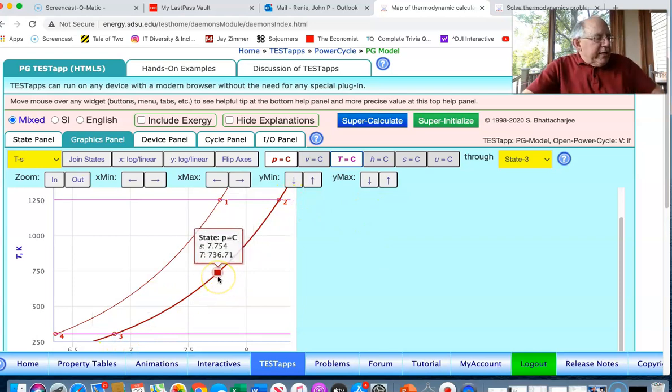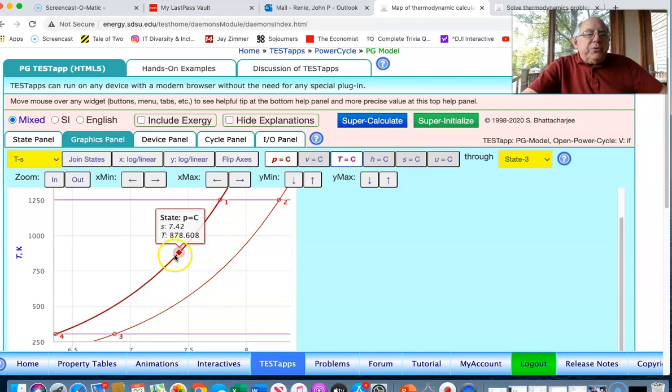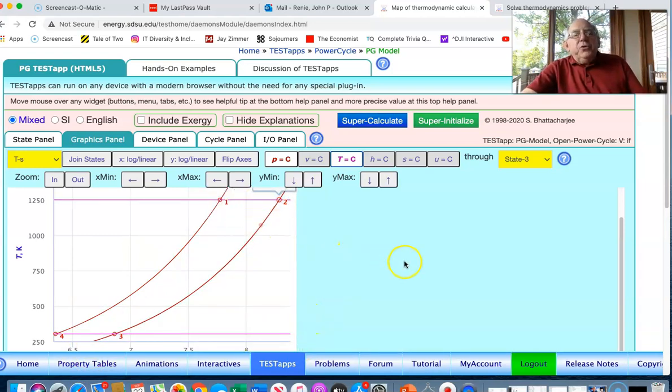We have heat transfer leaving the system going into the rise of temperature between 4 and 1. And so there's a regenerative nature between those two. And then the heat transfers between 3 and 4 and 1 and 2 are just the reversible heat transfers, either rejected in the compressor or added in the turbine.